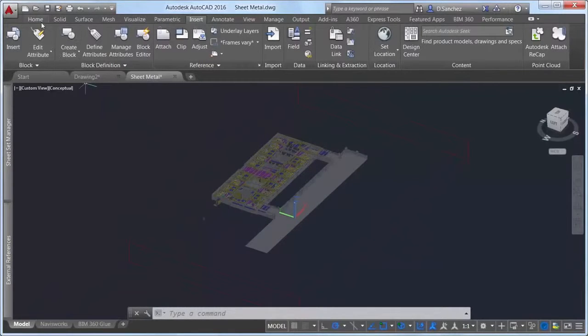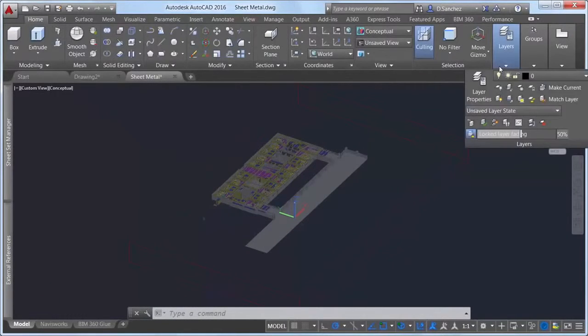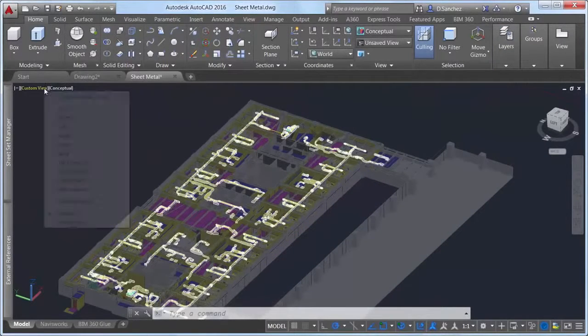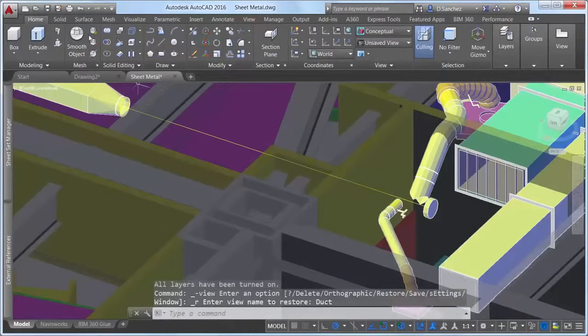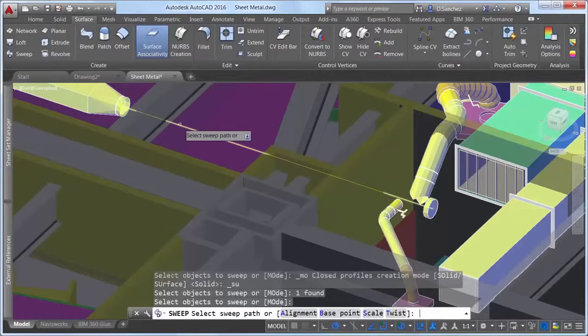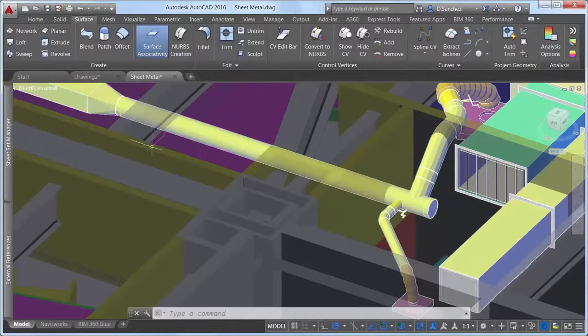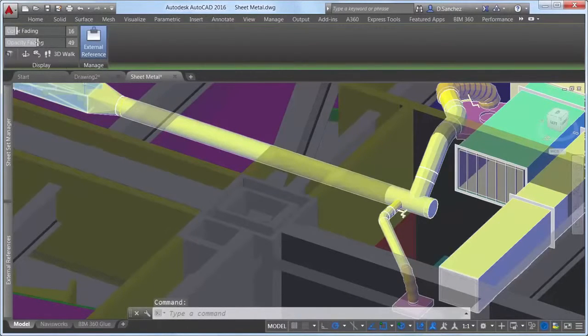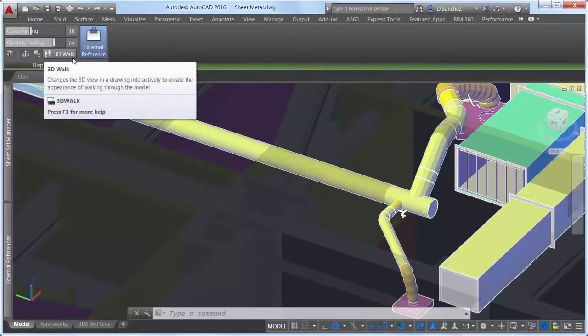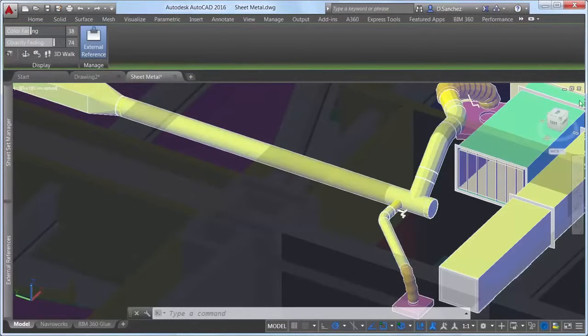With the Navisworks file attached, you can create, view, and edit the current AutoCAD drawing within the context of the model. Selecting the model displays the Contextual Coordination Model ribbon tab, where you can control the color and opacity fading to visually differentiate between the drawing geometry and attached coordination models. Color fading controls the amount of black blended onto the coordination models, and opacity fading controls the amount of transparency. Additional controls on the Coordination Model ribbon tab provide easy access to 3D navigation tools.